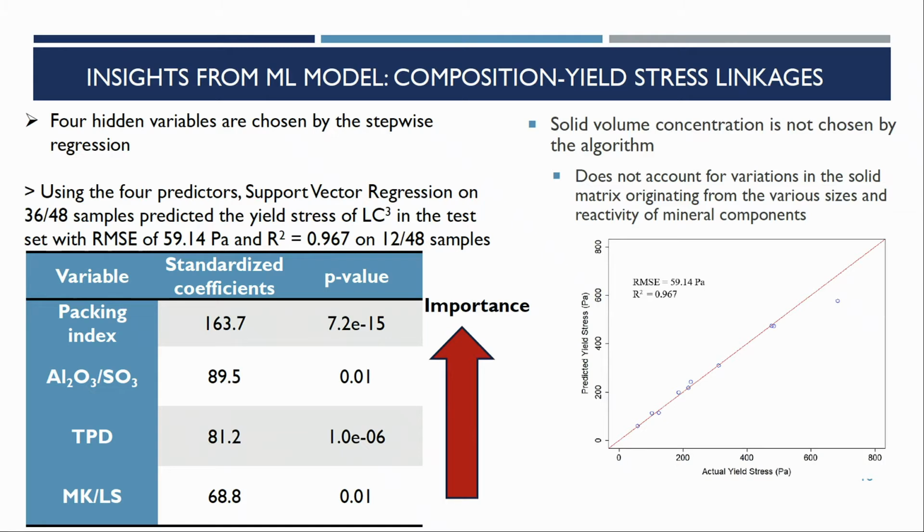At the LC3 conference, I went to a very interesting poster on using machine learning to predict compressive strength of LC3, and the folks there had about 100 data points, and they augmented it through some numerical sleight of hand. That's fine. And then they basically took this augmented data set and threw it against 120 different machine learning algorithms, because that's what you can get in Python at this point. And then they picked the one that had the highest R squared, and that was their result. What I would call that is basically R squared engineering.